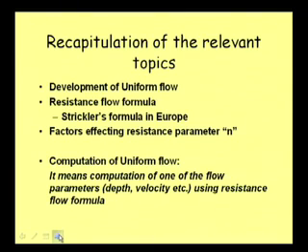Well, just to recapitulate what we did in the last class, we studied the development of uniform flow. Before the uniform flow gets developed, there may be some portion of transition, and then gradually it comes to a uniform flow pattern. In a channel, when there is some change, the flow gets disturbed again, and when there is a long reach without any change, we normally get uniform flow, and that depth of flow we refer to as the normal depth.